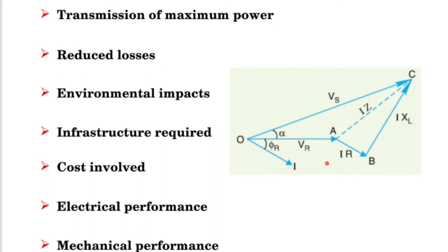So all those inductors or inductances present in the circuit will cause some reactive power flow, meaning because of the inductance, due to the magnetic flux in the transmission line conductors, they will be drawing reactive power, meaning someone now will need to supply that reactive power. Now, where will that reactive power come from?